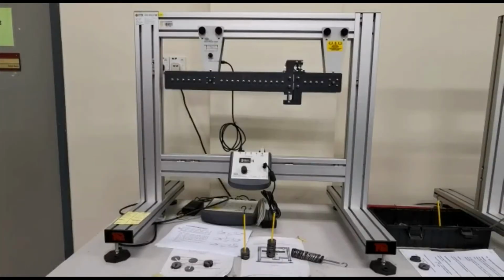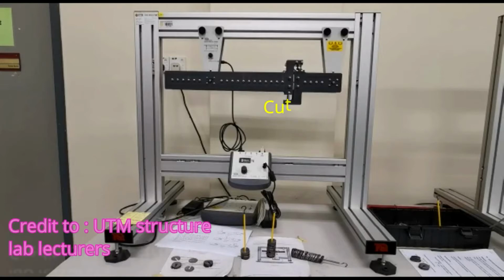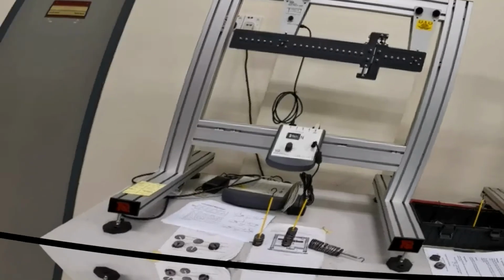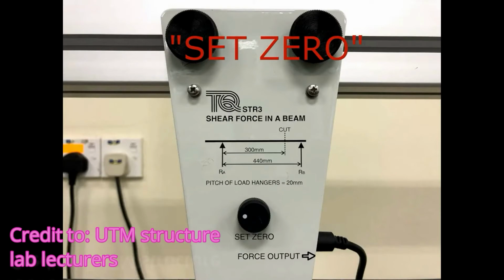The original experiment setup is as shown in the diagram. The cut section XX is between support B and C. Digital meter display is to show the shear force at cut section. Loads are also prepared with hangers and mesh. Calibration is also important to be reset to 0 for accurate data reading.